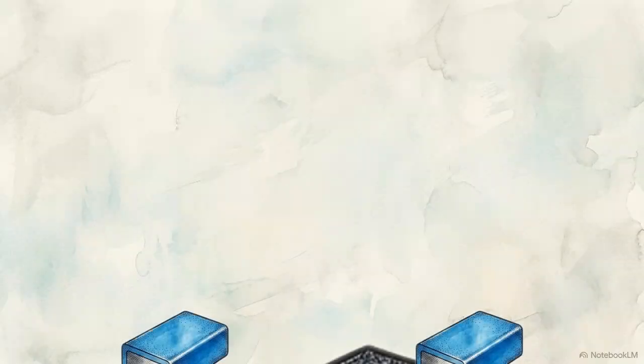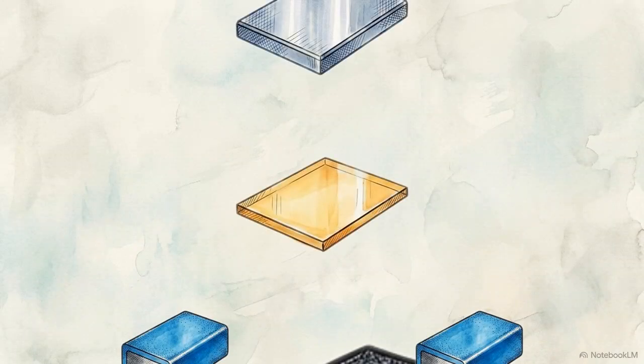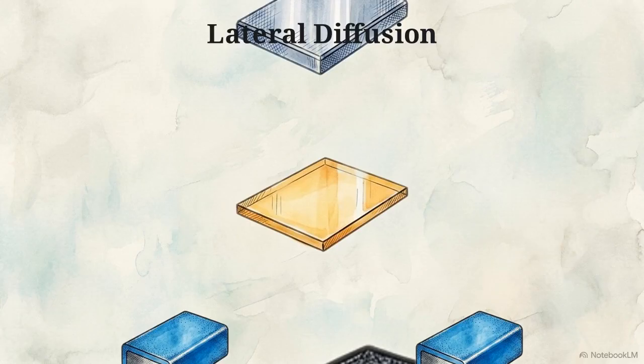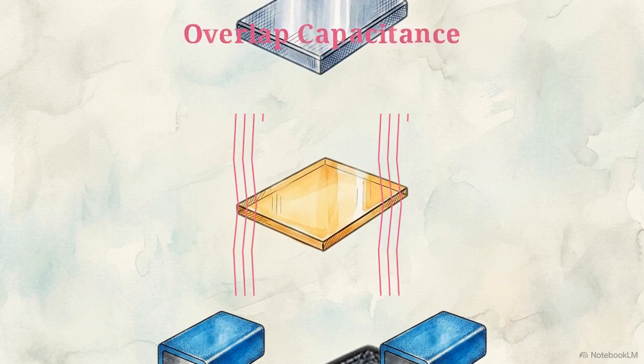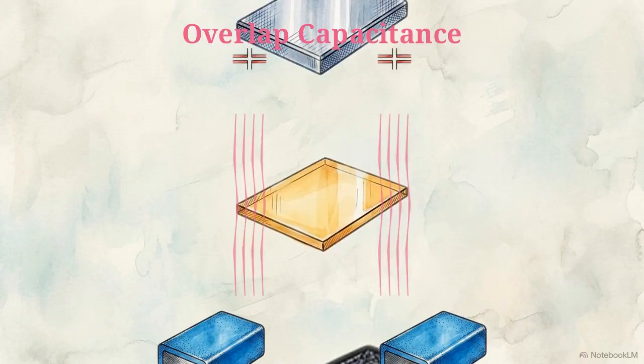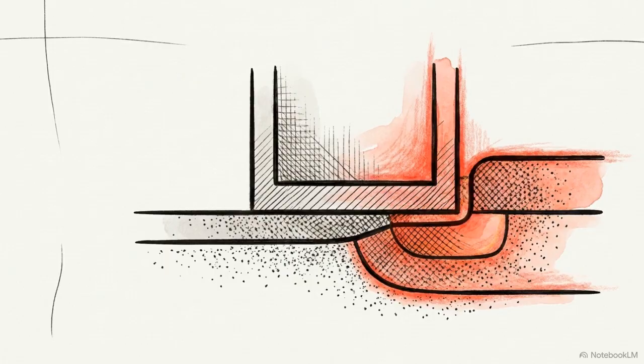Other parasitics reside at the physical boundaries where the gate edges meet the doped source and drain regions. During fabrication, high-temperature doping causes lateral diffusion. The source and drain regions spread horizontally, slipping slightly beneath the gate oxide. This results in a fixed electrostatic connection in these overlapping regions, known as overlap capacitance. This overlap is particularly impactful at the gate-to-drain boundary due to its effect on switching speed.